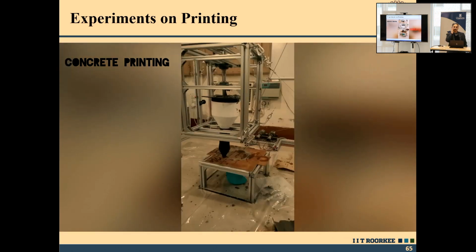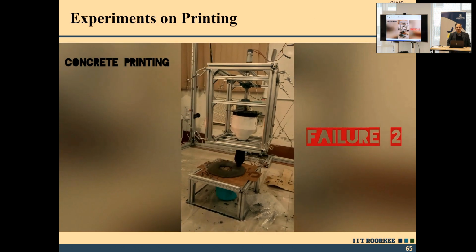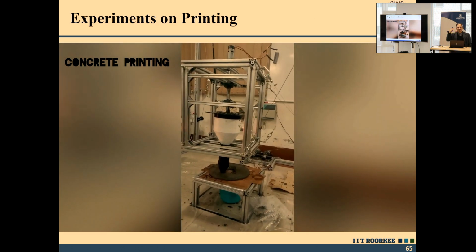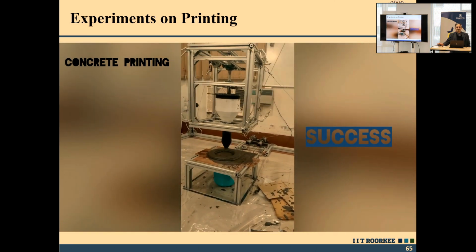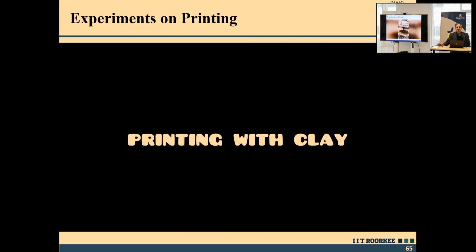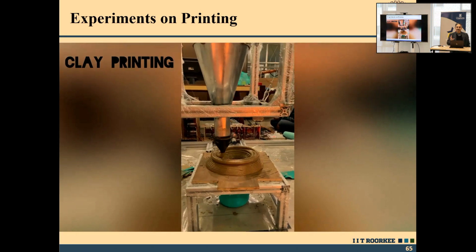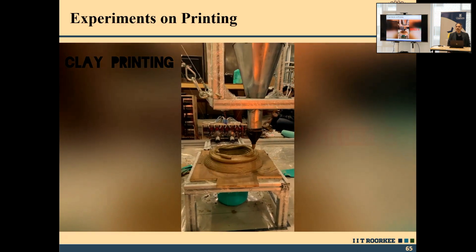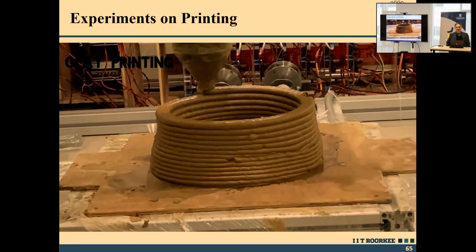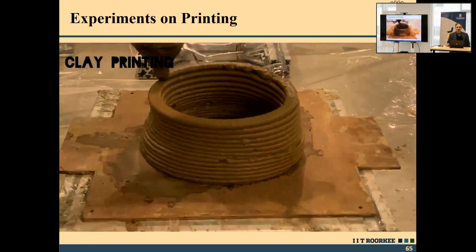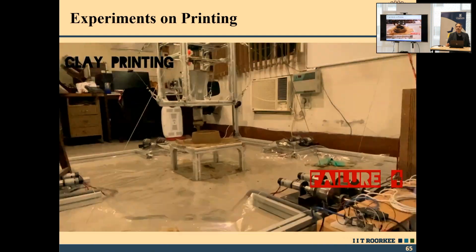We had many failures actually. We were not sure about what the mixture ratio should be. So, this was the concrete printing. Then we tried printing with clay also. Again here the moisture was an issue. Initially we did not know the exact moisture content, the water content of the clay, but later after several trials we could figure it out.